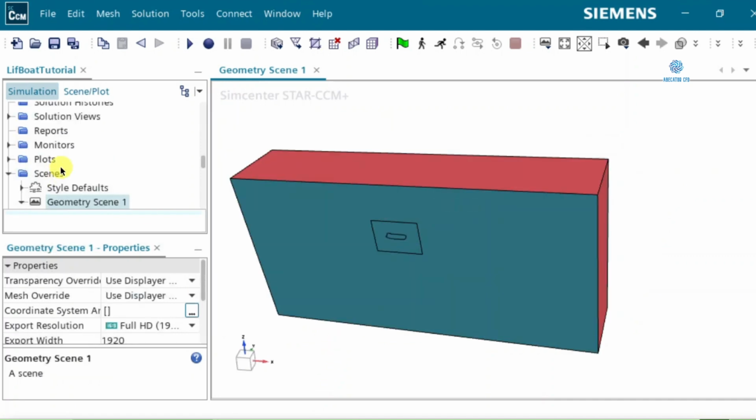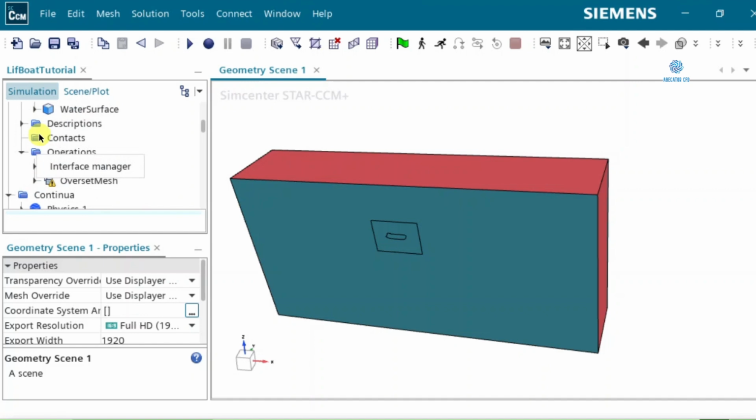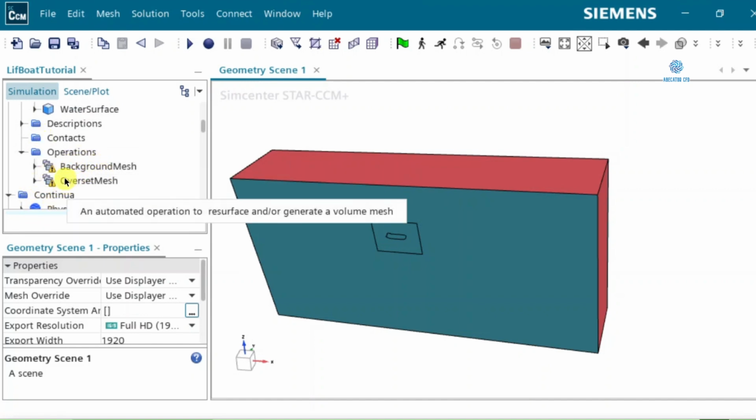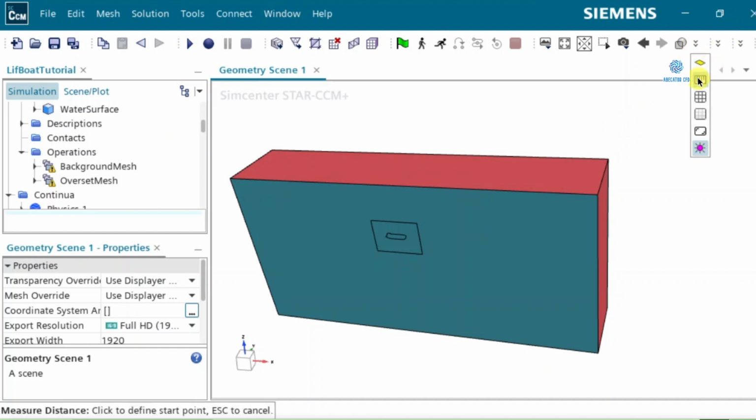Now, at this stage, we want to apply the dimensions and mesh sizes. We apply those settings to the mesh operations before moving on. Before that, let me first build an intuition for the sizes we are using. From the top toolbar, select the ruler tool.